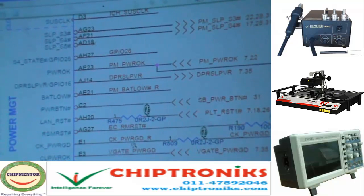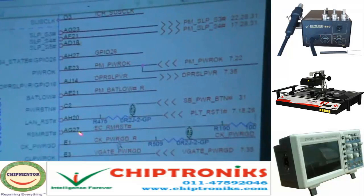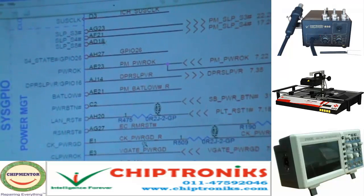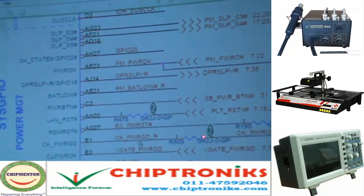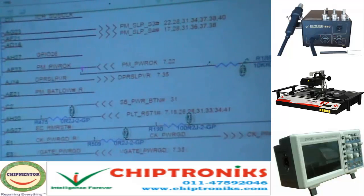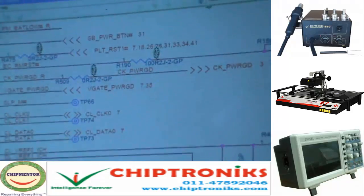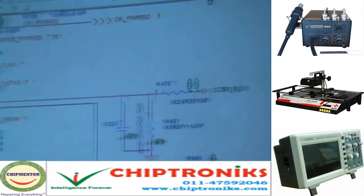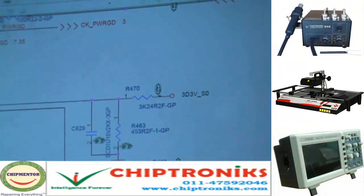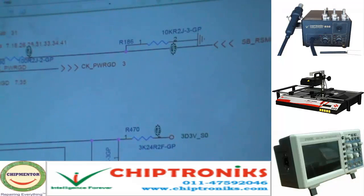Clock power good. This signal is fed to the clock generator. After this signal gets to the clock generator IC, then the clock generator will start. So here we have covered all the important signals. We will go to the last page. Let me see if I am missing anything over here.